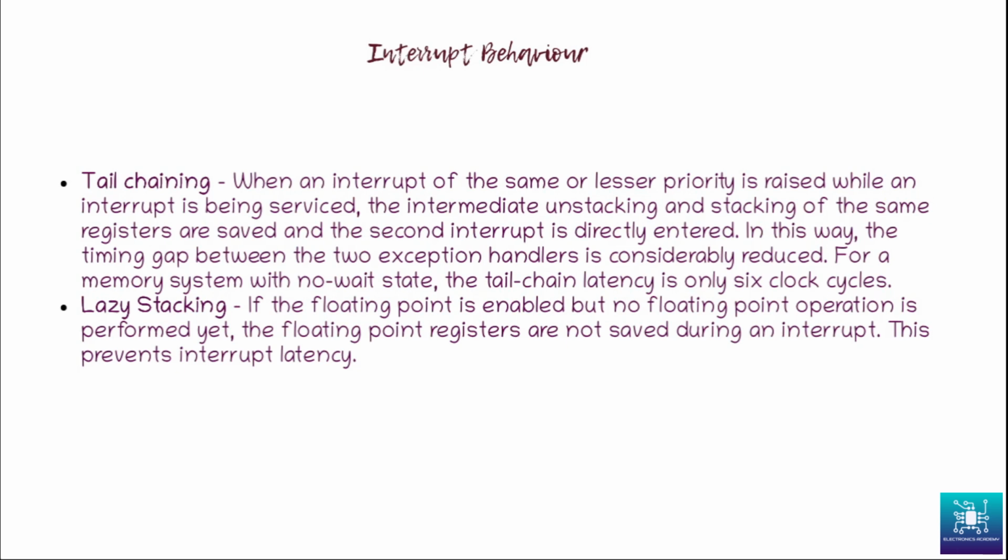Here, it's the same or lesser priority. So, of course, the first interrupt will have to do an unstacking, and the second interrupt on entry will have to again do a stacking. But the unstacking and stacking would be of the same set of registers. The second interrupt will have to take the same set of register values and stack them again. So the stack just extends and contracts, and it's pretty much the same thing.